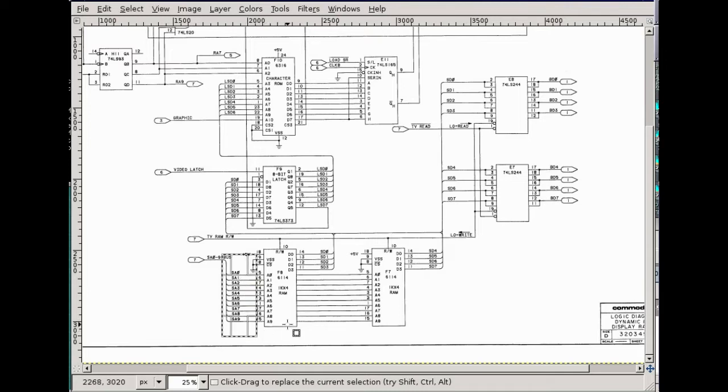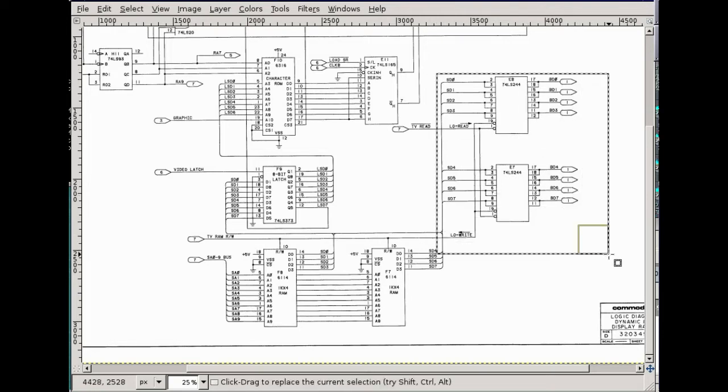because when the CPU is not executing, the screen address is only scanned from the video output circuitry, and we'll see on another page how this is made. Another thing that is more likely, in my opinion, is a problem with the data bus transceivers.